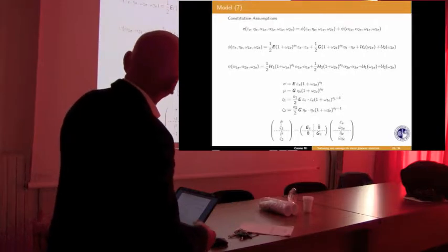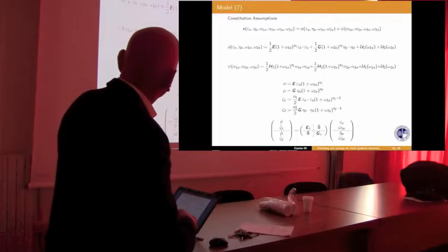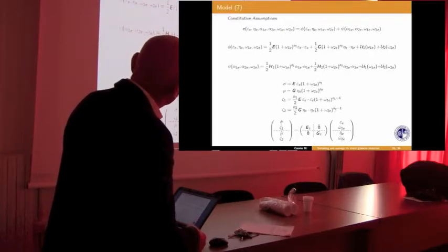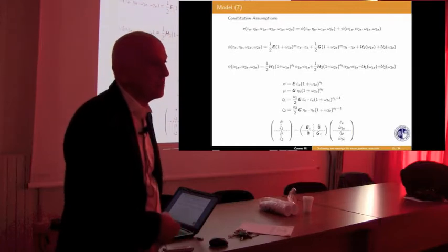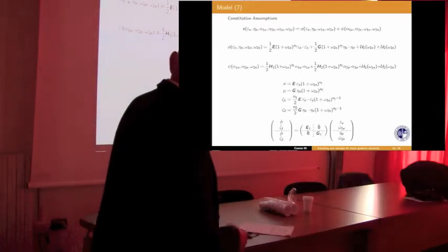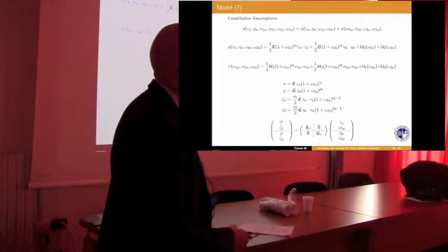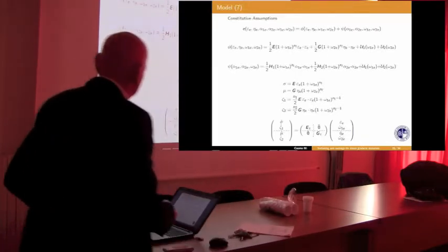There are two other equations that we have not written for the thermodynamical forces dual of the hardening variables. I assume that the stresses and hyperstresses and the other thermodynamical forces are uncoupled. This is not necessary, but it's a common assumption.